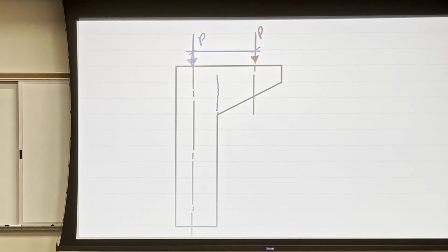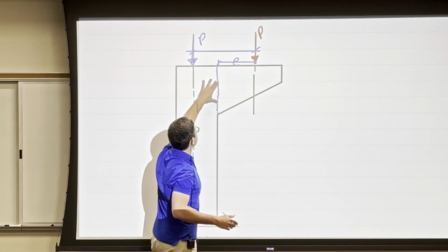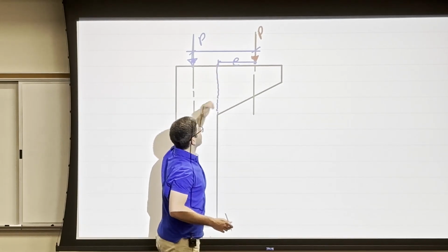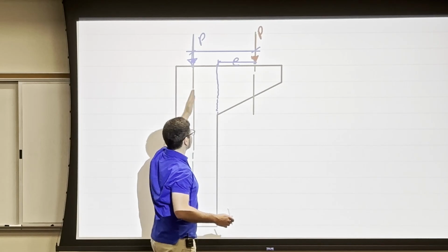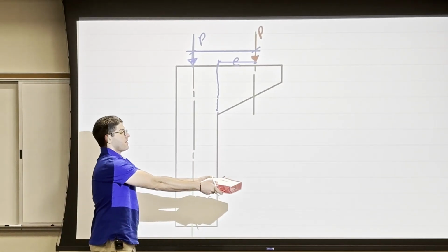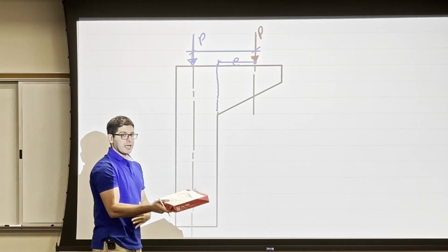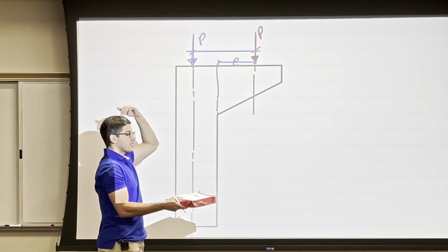But here is a common mistake. The common mistake is you multiply by this distance, which is to the edge of the column. No, the edge of the column doesn't support the weight of this load. Instead, you want to move the load to the center. Same as this paper example. In this paper example, the edge of my body, the skin, doesn't hold the weight. Instead, the core of my body, which is like the center.